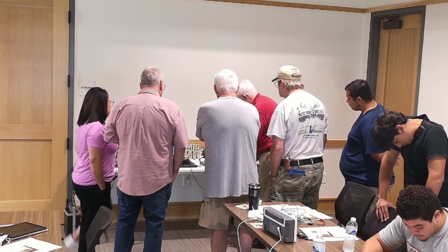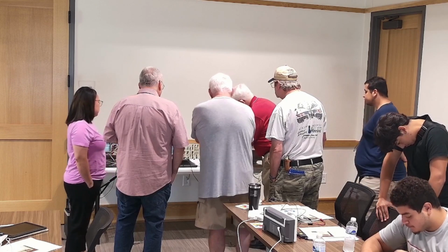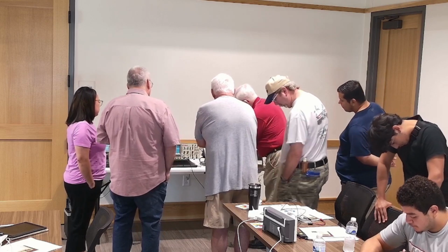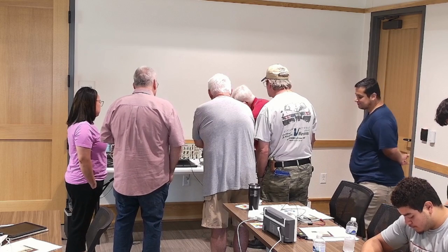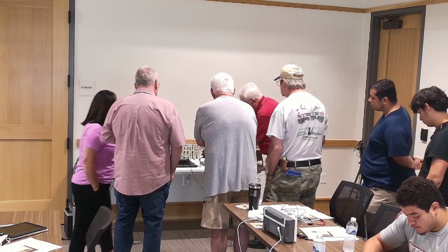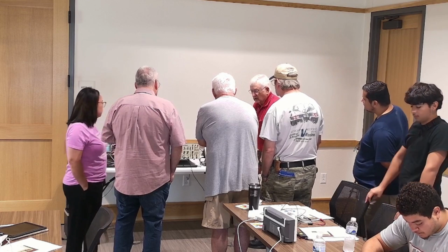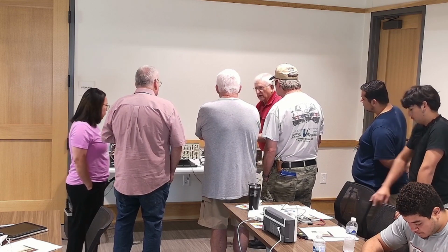So again, we're looking at 5 volts per division. Let me put that right on the line there. So that's 5, 10, 15. It's actually about 20 volts coming out of that because it has no load on it. Now, if I put a resistor across these two leads, that should drop back down to about 5 volts.